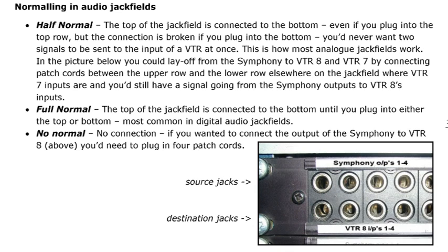And that's most often found in facilities where they have digital video distribution. Digital audio distribution and analog audio distribution typically go via the same style of patch panels. They use the same patch panels to patch them, the same connection cables, and pretty much the same kind of cables between the jack fields and the back of the equipment.